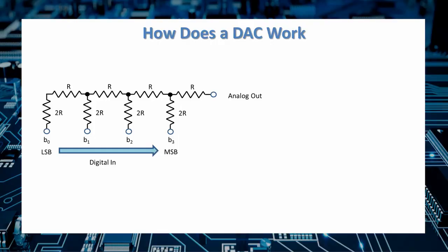At the heart of most DACs is a resistor network that converts a byte of data into an analog voltage. The resistor network is set up in such a way that each bit in the word contributes a proportion of the voltage equal to its position in the word. For example, the most significant bit contributes the largest. The bit just below that contributes half of what the most significant bit contributes, and so on and so forth as we move down the line. The resolution of the DAC is controlled by the number of bits. This example shows what would be the resistor network for a 4-bit DAC.